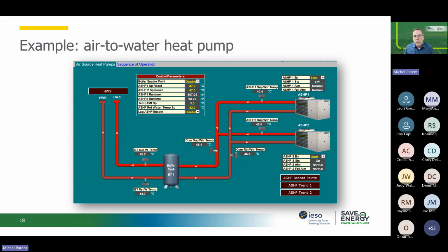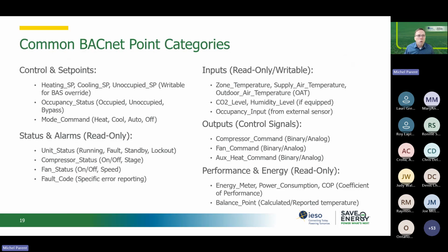Make sure you test them. I don't have that example, but communication is key. When you integrate a BACnet controller, make sure communication is fully commissioned and tested. There are lots of points available, but the integration needs to be properly commissioned.